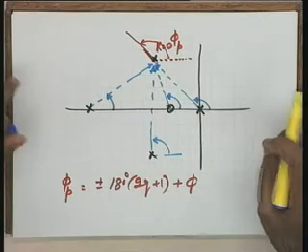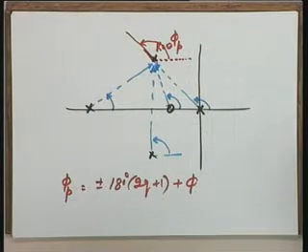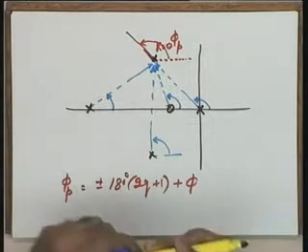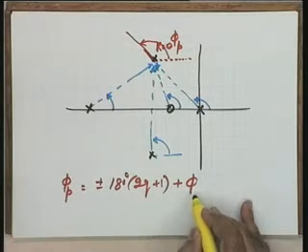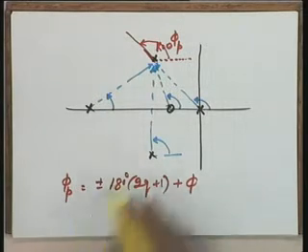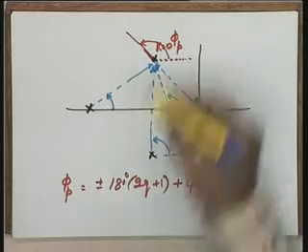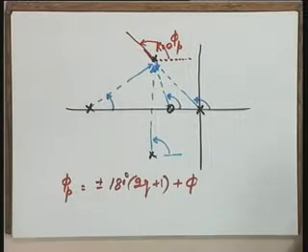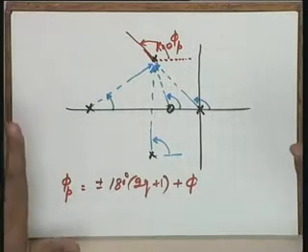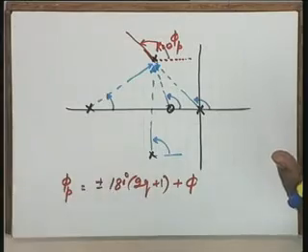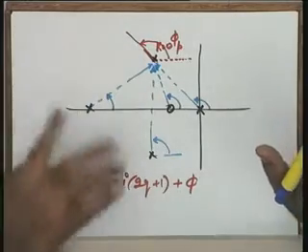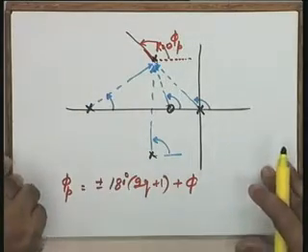So calculate the total angle taking suitable algebraic sign into consideration, positive sign with the zeros and negative sign with the poles. Let us say that total angle turns out to be phi. In that particular case, the root locus will leave this particular pole at an angle phi p given by this formula. I hope this is clear, and this will be exemplified. Let me not give an example here. I am going to take a comprehensive example in which all the rules will be revised. So naturally this rule will also suitably come up there.